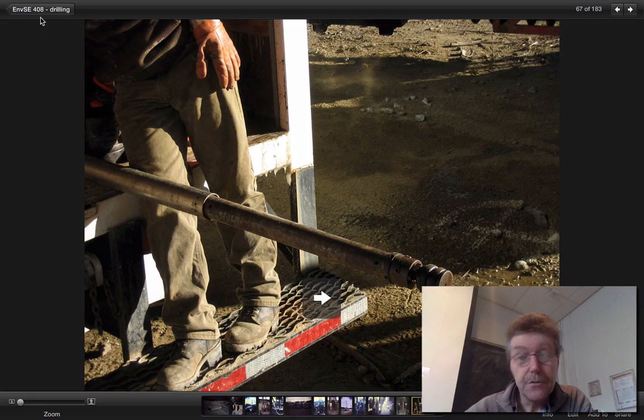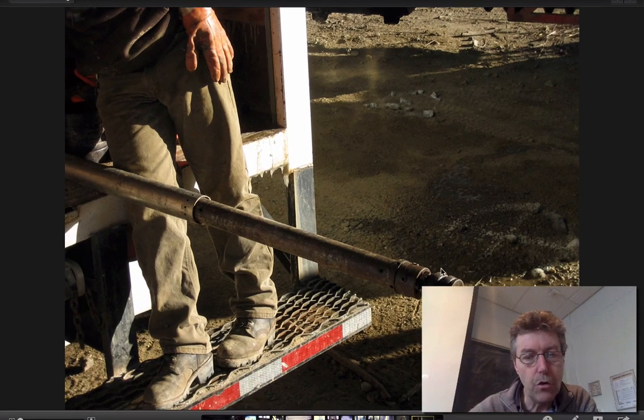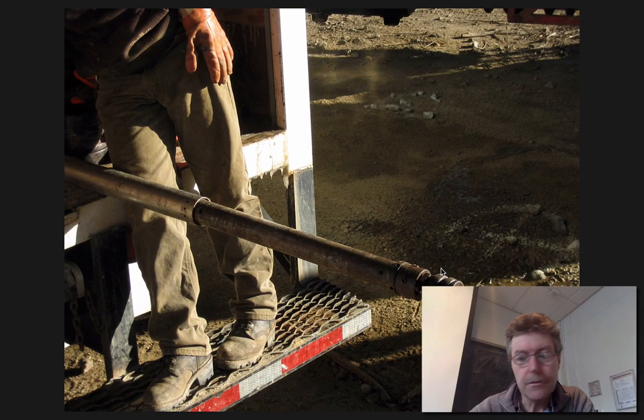This is the last form of drilling. Yeah, this is exactly what this is. This is the tool. This is the piston. The shaft of the piston is in here. You put on here the Shelby tube, which might be another 2 feet on the end of it. You can see, maybe if you trust me, that this portion here is a bit of latex that goes against the wall to be able to guard against that.